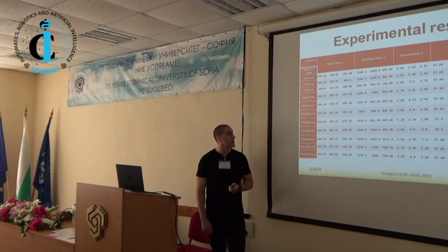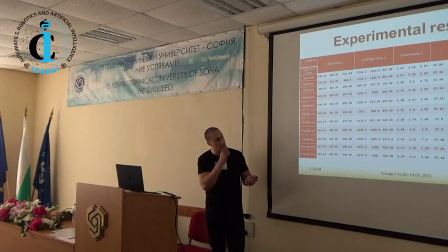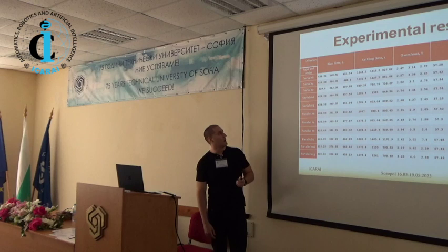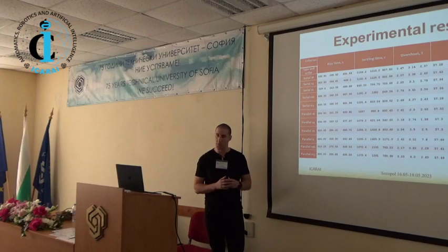At the end we calculated some criteria like rise time, settling time, overshoot, and here we have the square root of the sum of the squared error, and this is the square root of the sum of the control signal. Looking again at the numerical results, we could see that there is quite some similarity between the closed loop control systems, despite their reduced order, which supports our idea that for simple plants it is possible to reduce the order without losing too much of the performance itself.